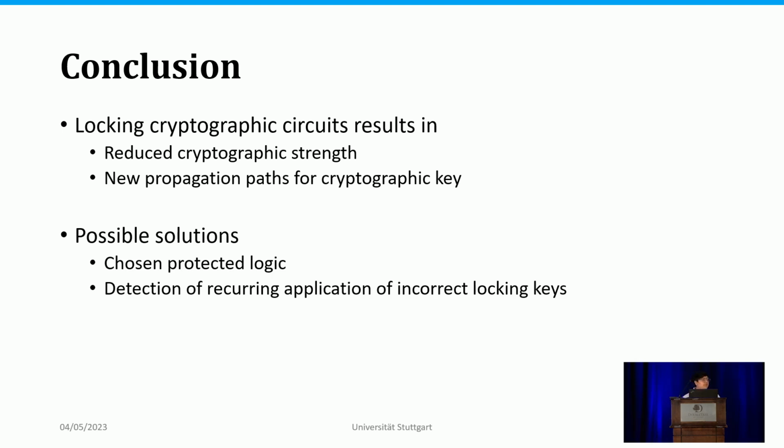And even though logic locking schemes were not introduced or developed specifically for cryptographic circuits, there is no existing work that explicitly excludes them. A part of a cryptographic circuit could be a part of a larger IP core that the designer might want to protect using schemes like logic locking. Therefore, the designers must stay clear of adding locking key gates at critical locations in the cryptographic circuits, and especially prevent cryptographic key bits from being fed directly into the locking subcircuits.